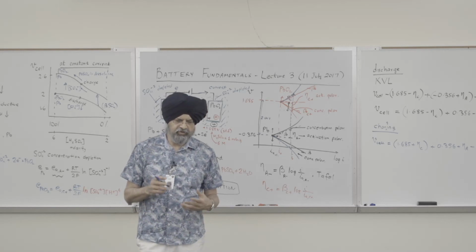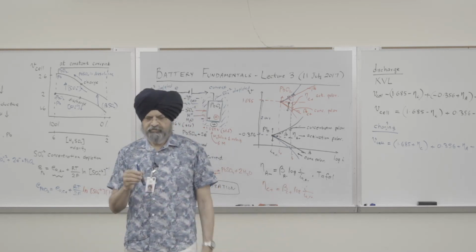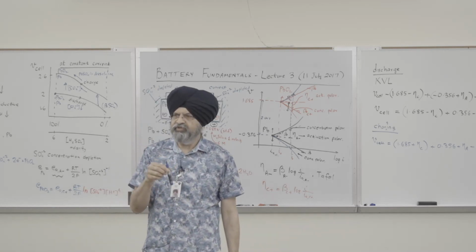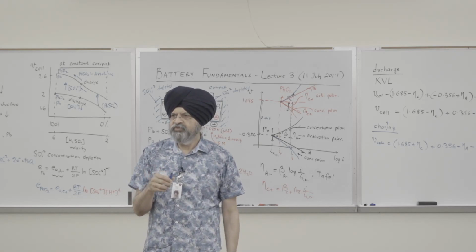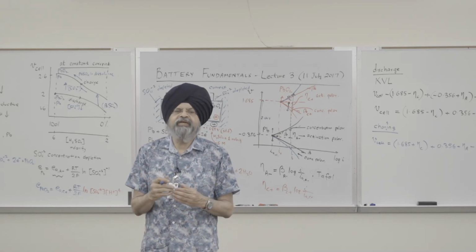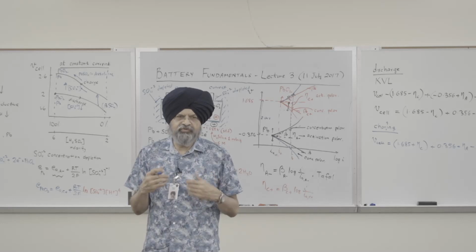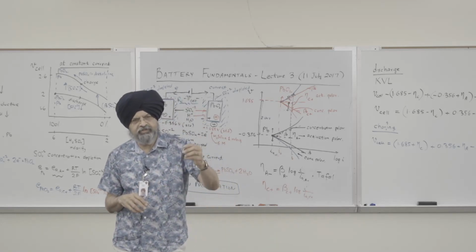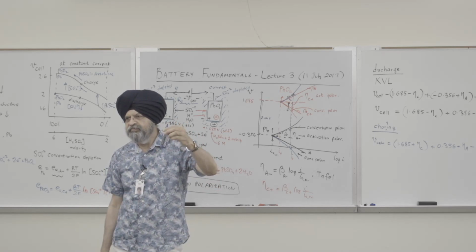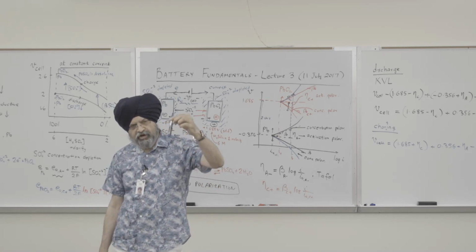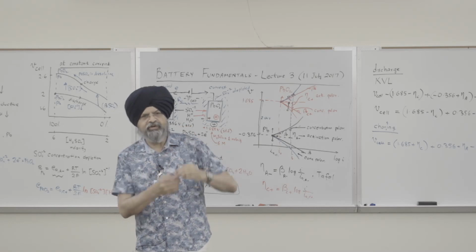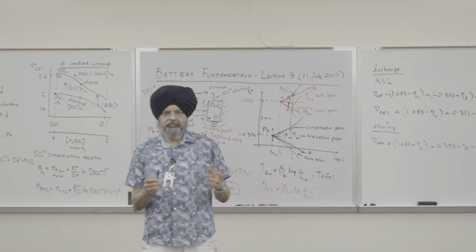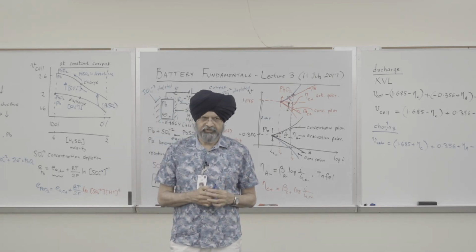And we measure the concentration of sulfuric acid by measuring the specific gravity. So when specific gravity increases, we know its concentration is higher, right? So people, they'll put this bulb in the electrolyte, see how much it floats, so you know what its specific gravity is. From that, you know the concentration.